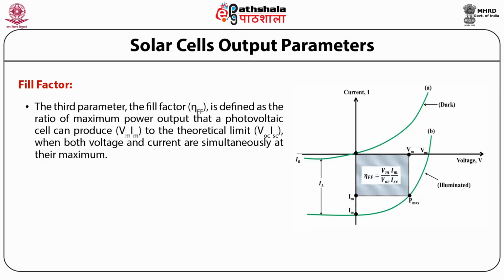So the fill factor, eta FF, is equal to VM IM by VOC ISC. The fill factor is a measure of how square the output characteristics are.